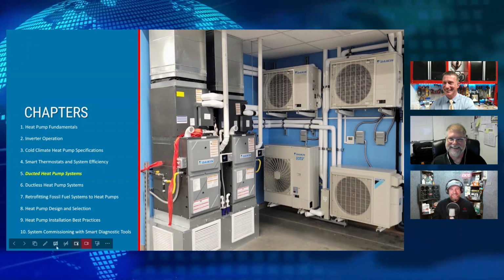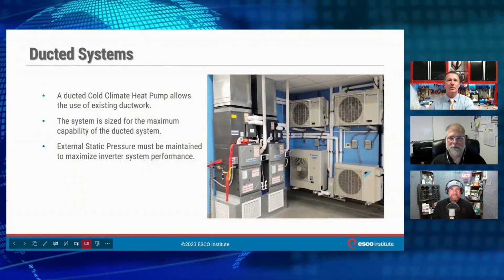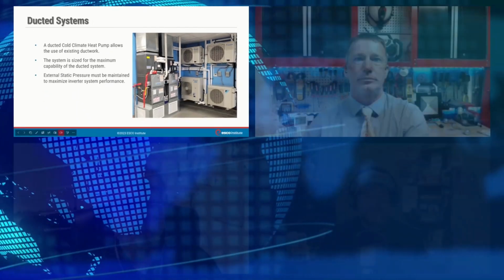I love it. It's one of my favorites. One of the things I hear from people all the time is, well, they just don't build equipment like they used to. And I said, well, maybe not. Are you installing it, checking the airflow, checking these other things? They said, well, oh no, we don't have time for that. I said, well, you cannot blame the equipment if you're cutting corners yourself. You first have to control what you can control. If you're not installing it right, we cannot blame the equipment. So we have to first do that first step of doing it right, doing it how it's supposed to be, fixing the airflow.